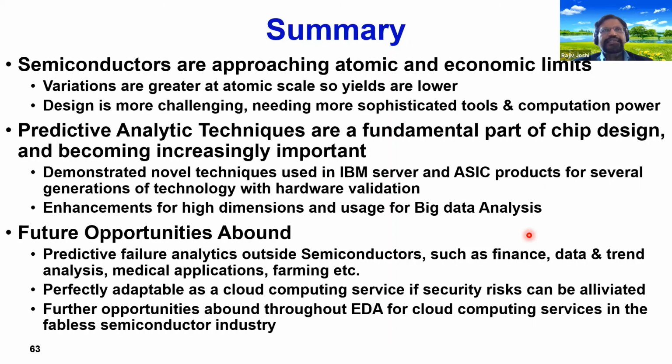And that's exactly where these ML techniques will be useful. You know that there are companies which have these products, and I will not go into the details of those companies. Those companies are using machine learning techniques for yield predictions and characterizing. So to answer your question, we will continue to use these ML techniques for standard cell delays especially, and for the latches, the timing of the latches, the writability of the latches, all kinds of things in that direction.